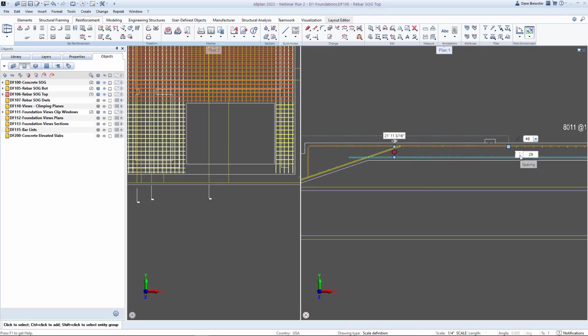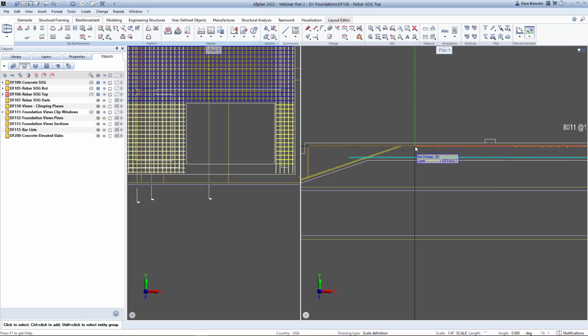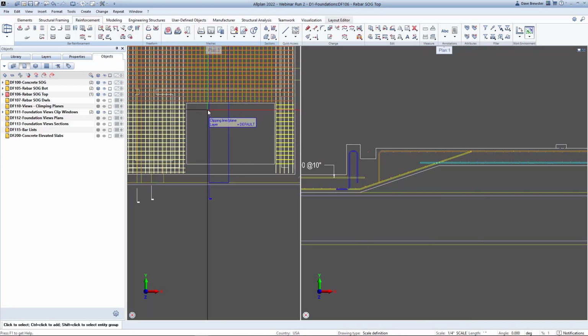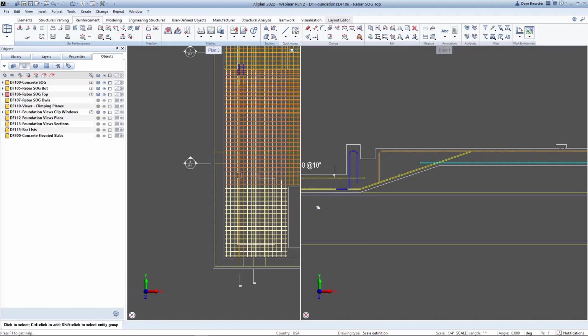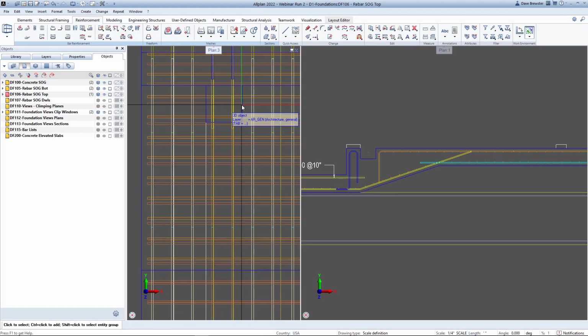So go back to your direct object modification. Use the same ideology here, no calculator needed. Let's change the spacing, type in 10 inches. And now, whatever it says, add 1 bar. It comes up and says, actually, it was 27 you needed, so I'm going to add 1 and put in 28 bars. Now I've got the proper number of bars I needed, and it follows the same logic as with the bottom bars replaced.